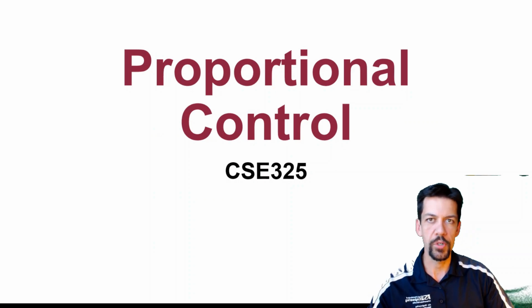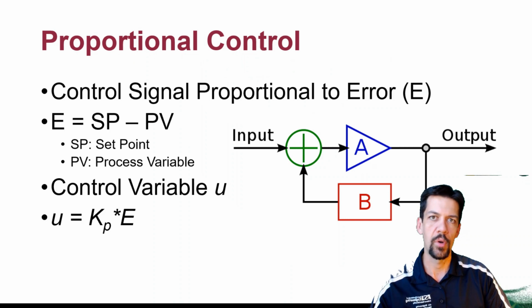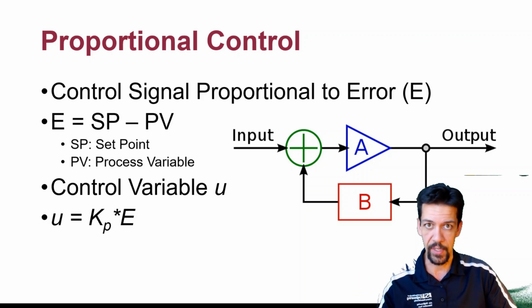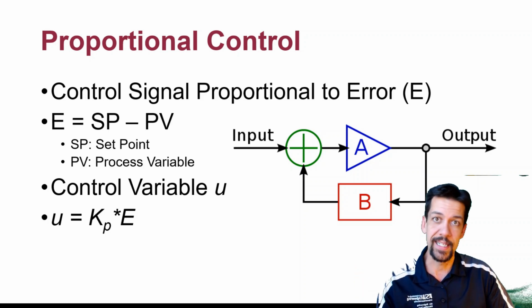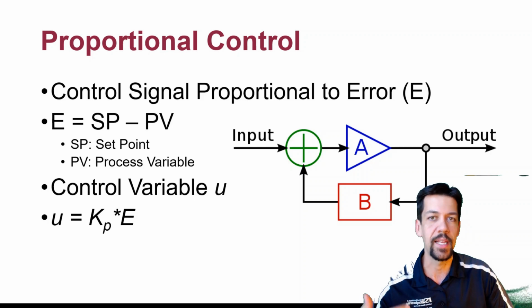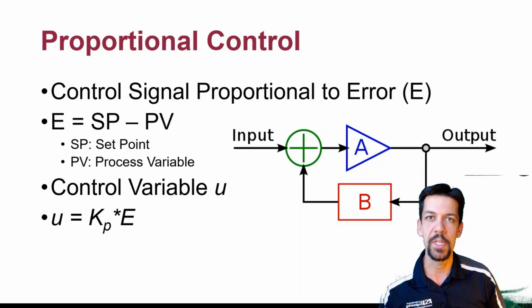Now let's talk about proportional control. This is a little bit more nuanced. In proportional control, this is a closed loop controller where the plant, or the system that we're working with, has some variability, has an analog sort of input to the system. So the control variable can take lots of different states, or is a continuous state rather than a discrete state. It's basically the simplest possible continuous controller, where our control signal is proportional to the error.